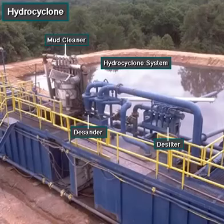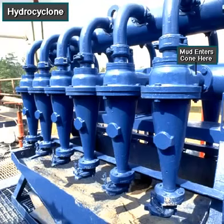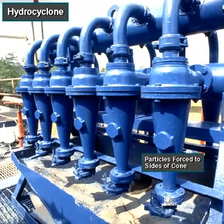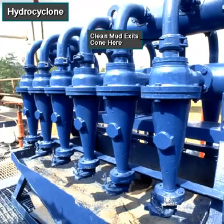A hydrocyclone system consists of several cones. Mud enters through a side opening at the large end of each cone. It swirls around inside the cone. This centrifugal force or cyclone motion throws the larger particles to the side of the cone. There, the particles move to the bottom of the cone and drop out. Clean mud goes out the outlet at the top.